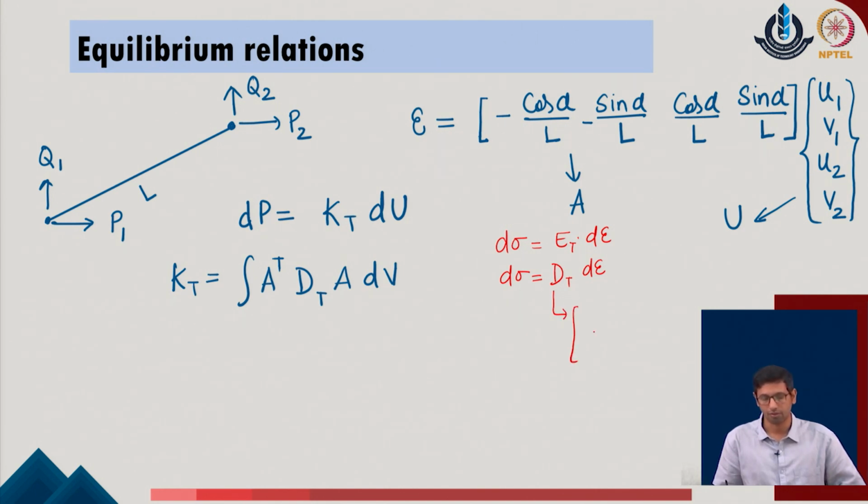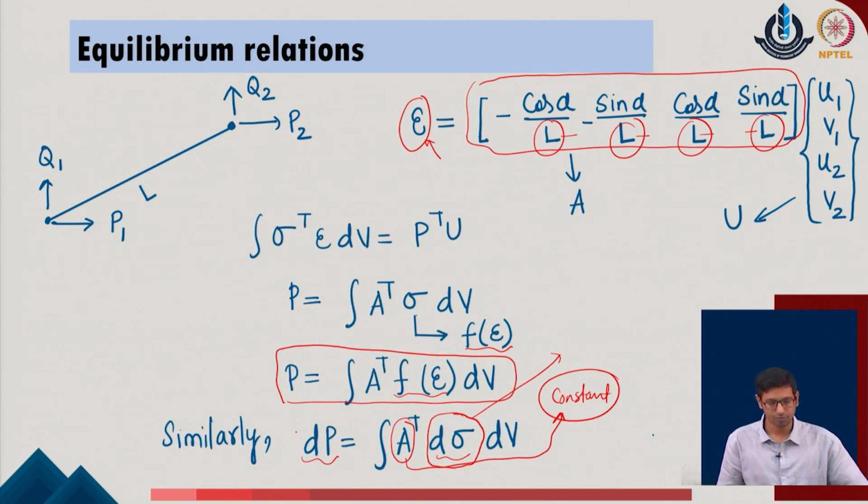So, again if you want to recall what is the d of t in the given system, we can just go back to the expression which we defined in the general beam formulation. We came up with something called as E A and E I as a flexural rigidity of the given system. So, this is representing that kind of a 2 cross 2 kind of a matrix. Only thing is that instead of taking the value of E in the given system, we are taking the tangent modulus of the given system. So, with this idea we convert the d sigma in terms of dt into d epsilon in the given form,